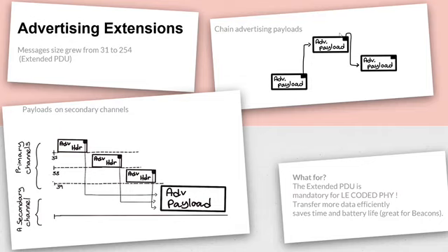Bottom left illustration. In BLE 4.2, the advertising was on the primary channels and the data sent during connection on the secondary. Since the advertising payload is so large now, a change was needed in the channel system as well. In Bluetooth 5, on the primary channels, you will find only the main header and a pointer that leads you to the first advertising data payload. That way, only the header is transmitting on the three advertising channels, and the actual advertisement is transmitted only once in any of the 0 until 39 BLE channels.